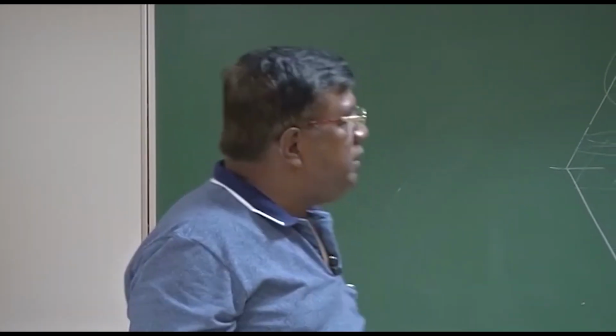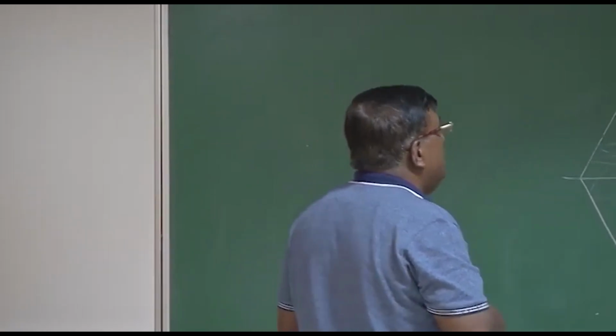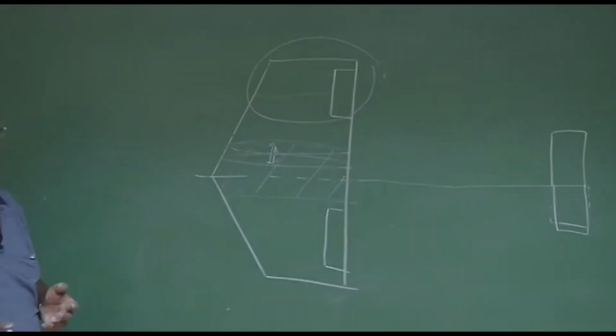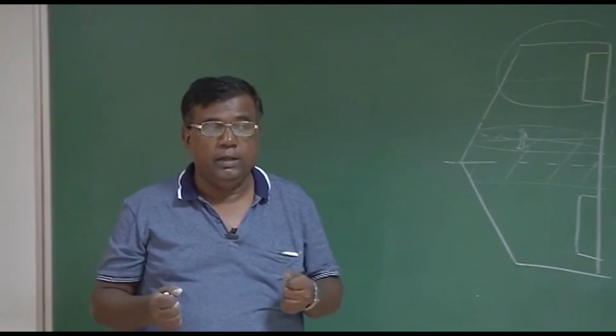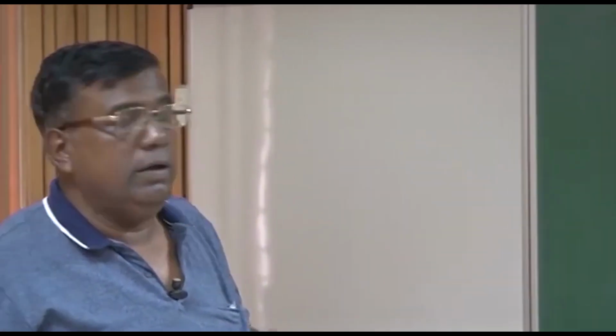So these are the small things which we need to take care in the design and make sure that you have enough authority given to the pilot to control it, to recover it from one point to the other, to ensure that he goes from one equilibrium to another equilibrium. If that is important, it is equally important also that from an adverse situation, it should be able to drive the airplane back to a normal situation.